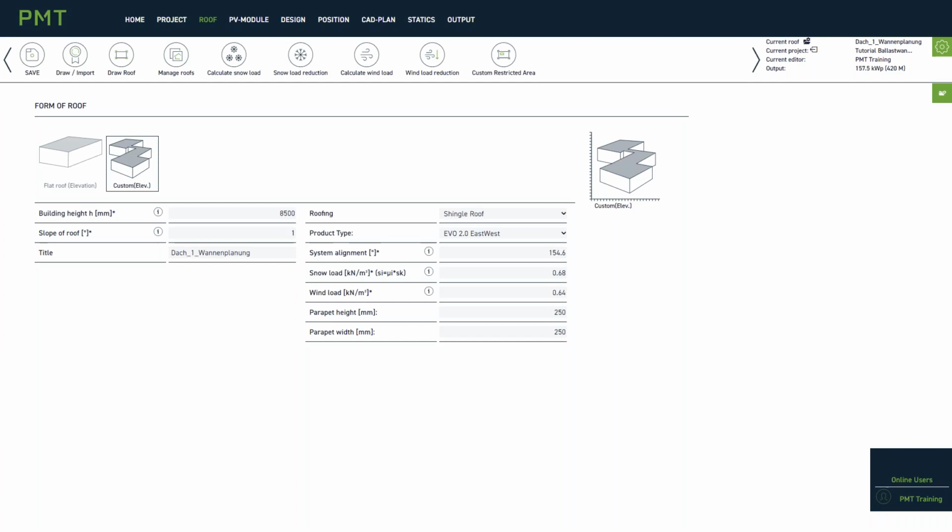You can lay out a ballast tray planning on already gravelled roofs or green roofs. It is also possible to build a PV system on the roof skin and provide it with gravel afterwards. The advantages of the ballast tray planning are the use of the gravel material as a ballast, which results in the reduction of the necessary ballast stones.